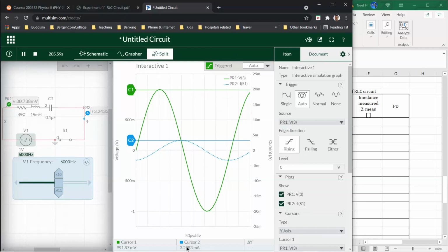Okay, that's why, depending on the numbers you use for the inductor and capacitor, that resonance frequency value changes. We know that it is 1 over 2 pi square root of LC. So I have to first know that number and then get an idea which frequency range I should search for to observe that particular behavior. Okay, that's important.